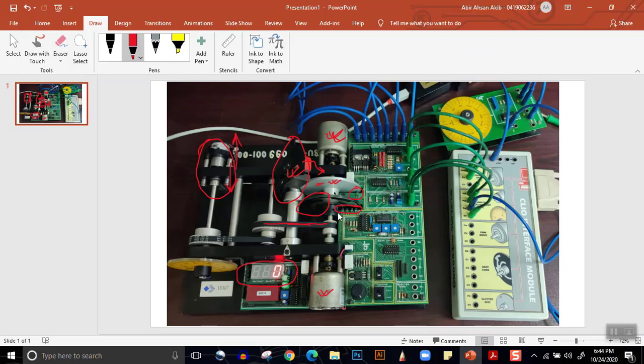If the LED is turned on and the reflected light is detected, the system understands whether there is a silver patch or a black patch in front of the LED. By finding this, it can determine the position of the actual rotary system. So position control is done through these photodetectors and photodiodes.